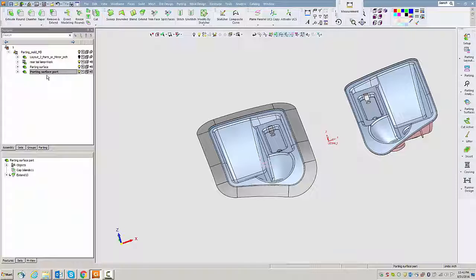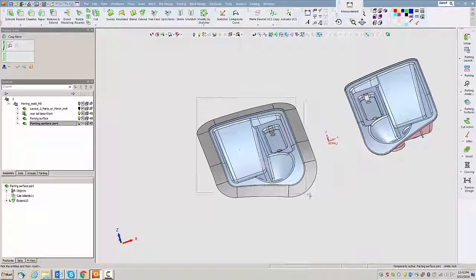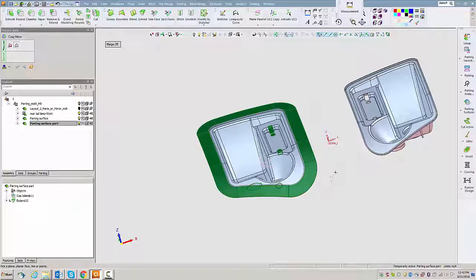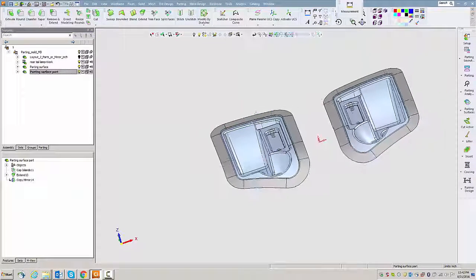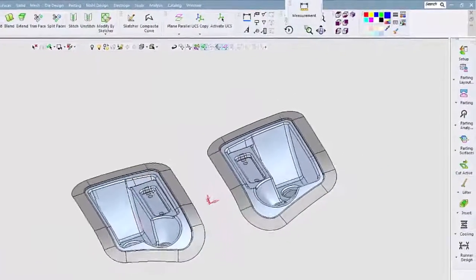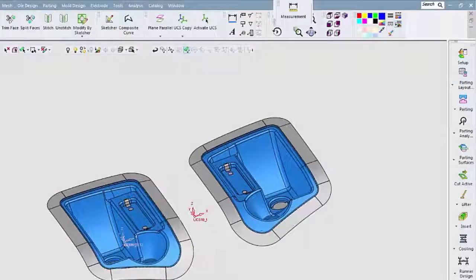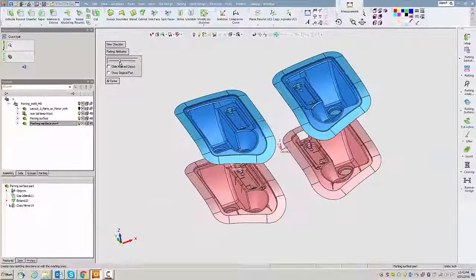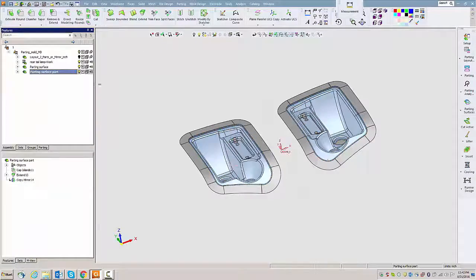In a previous video, we discussed using layout part for multi-cavity situations. So if, say, this were to be a four-cavity, we would have used a four-cavity layout when we started with the Mold Wizard. Using QuickSplit, we can see that all the attributes remain assigned to those copied faces.